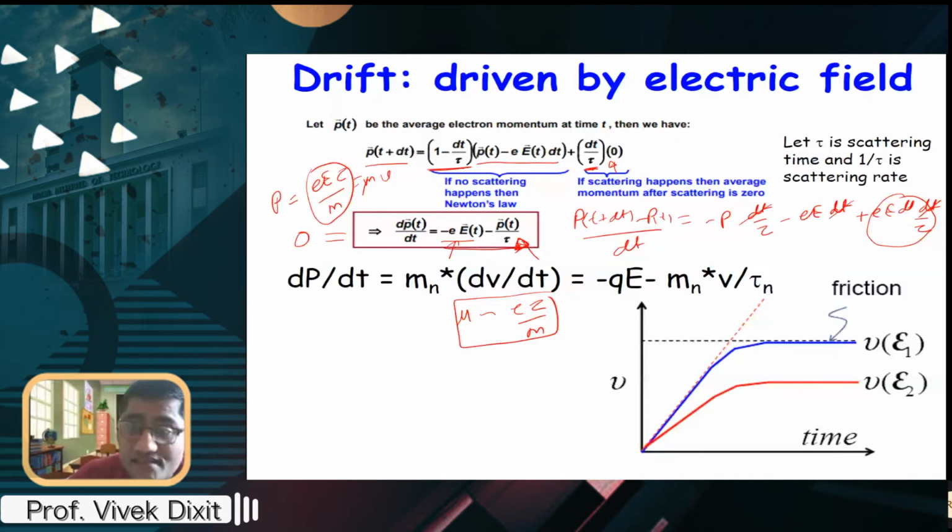Now, if you consider this velocity variation with time, this figure is a little misleading in the sense that electron velocity is never 0. At a given temperature T, the speed of the electron is never 0, right? It's already at thermal velocity, so electrons are already moving with thermal velocity in random directions. So the net velocity in a particular direction is 0, right? When you apply the electric field, it increases, and within a certain response time, you have this fixed velocity, called the drift velocity.